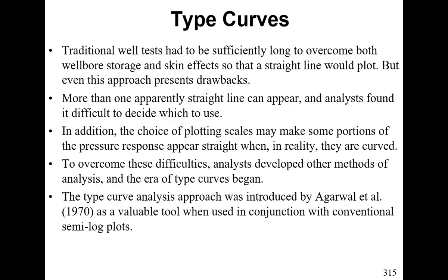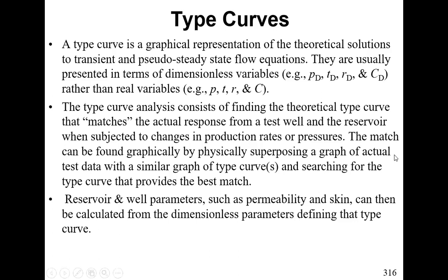And in 1970, the type curve analysis approach was introduced by Agarwal et al. And since then, it has been used in conjunction with the same conventional semi-log plots. So what's a type curve? A type curve is a graphical representation of the theoretical solutions to, be it transient flow or pseudo-steady state flow equations. They are usually presented in terms of dimensionless variables. And I think that's one key point, rather than real variables like we've been dealing with.